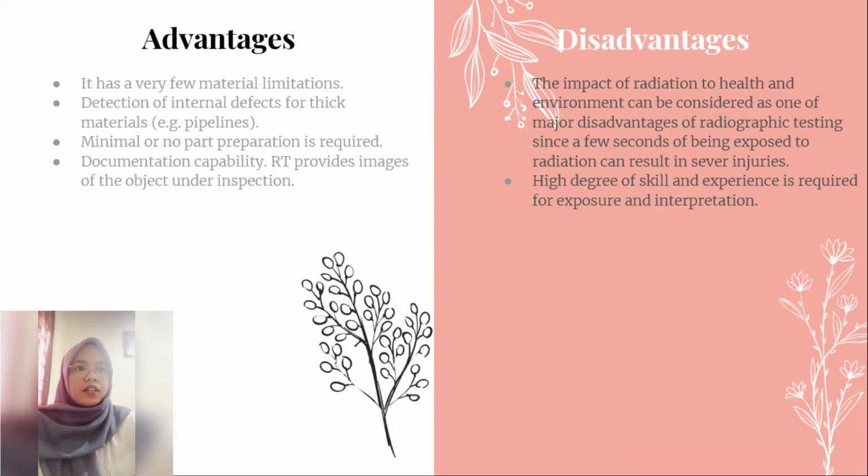The advantage of RT is that it has very few material limitations. It can detect internal defects in thick materials, such as pipelines. Minimal or no part preparation is required. One of the major advantages of RT is its documentation capability. RT provides an image of the object under inspection.